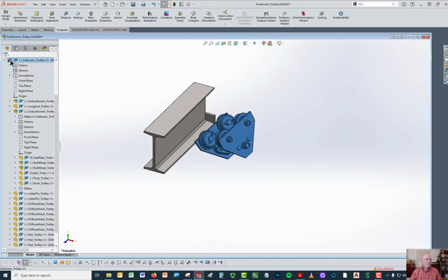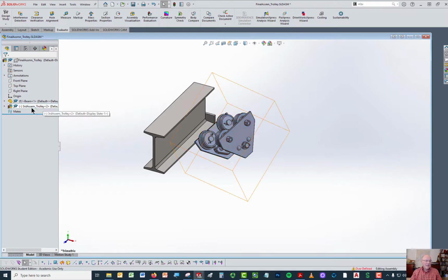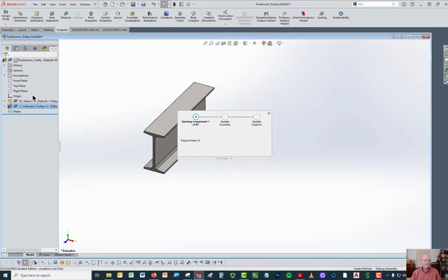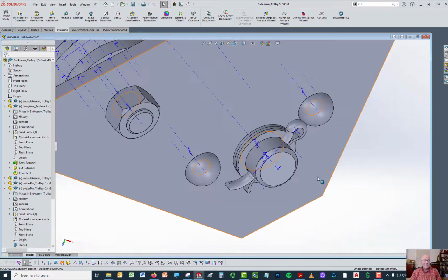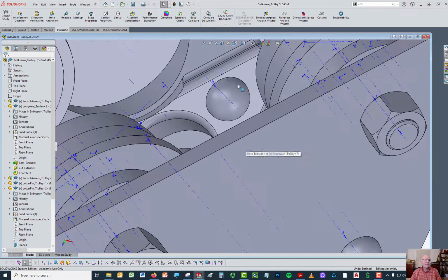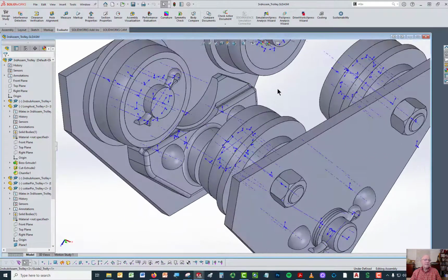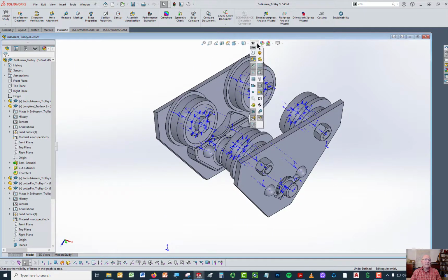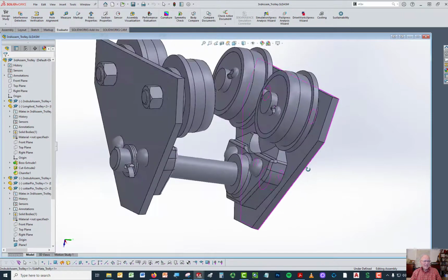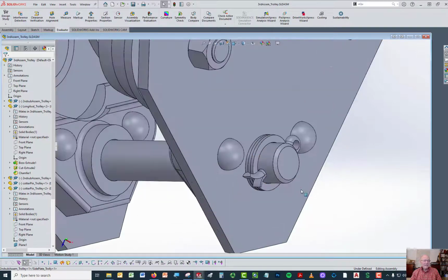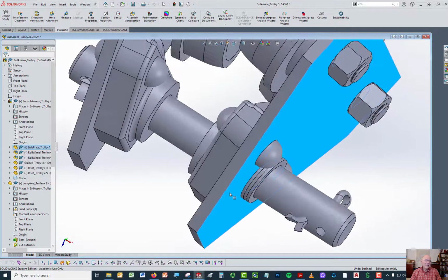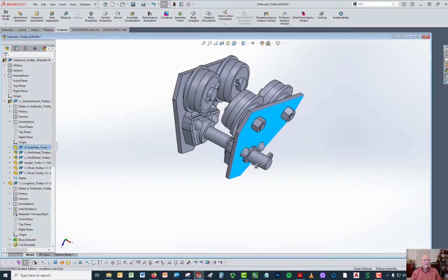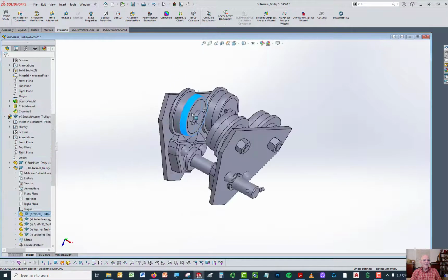So now I have to go back to one of the sub-assemblies to fix that. I'm going to right click on this and open that sub-assembly. Now here's the sub-assembly. There was some mating being done to temporary axes and to origins, so I'm going to go up to the little eyeball and turn those back off so that they're not in the way. But there's something clearly wrong here. Now in order to make this right, oh look at that. I'm able to move this all over the place.